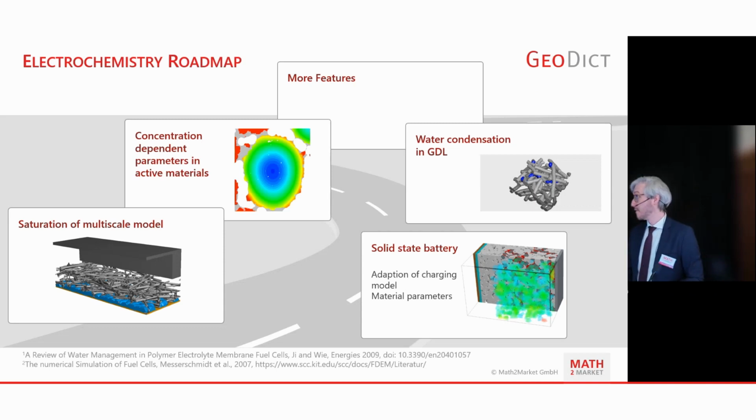In the electrochemistry business area, so batteries, fuel cells, electrolyzers, we work on concentration-dependent parameters in active materials. So this is very important to be able to really compare a charging simulation to real experiments, because the material properties depend very much on the actual lithium concentration we have in the active material.